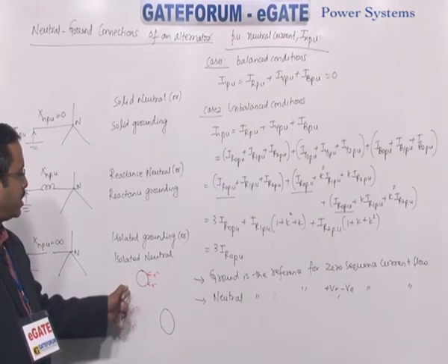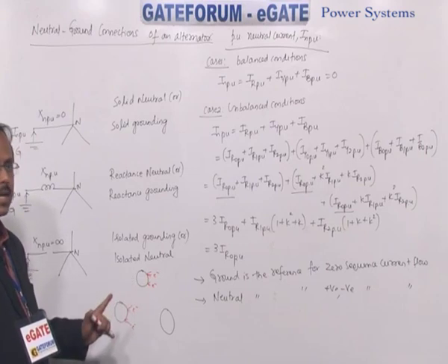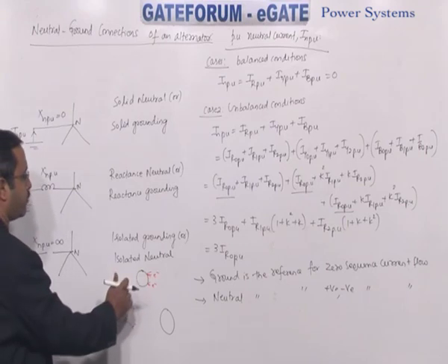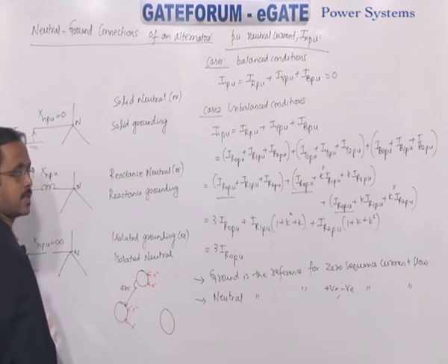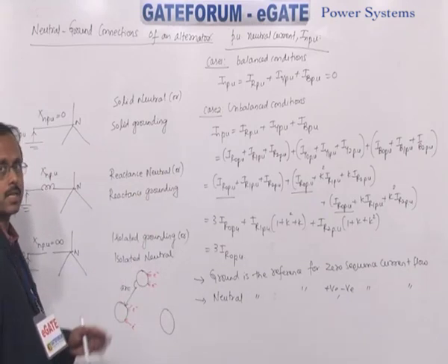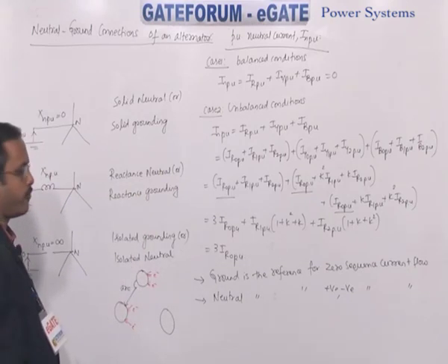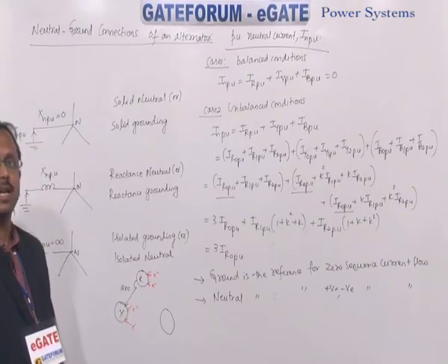The distance between the conductors also determines the corona, because if the conductors are in close proximity, an arc is struck between the conductors. If they are separated by a very large distance, there is no formation of arc between, say, the R phase and Y phase conductors.